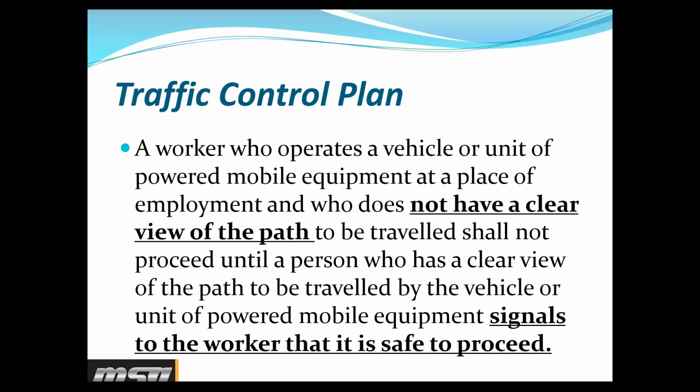These variables limit the clear view of sight and require the need for a signaler. I actually knew of an automobile dealership that drove into their dealership shop and they hit a fellow employee with a car because their windows fogged up and they could not see and they were not using a signaler. So again, this section really outlines the requirement for utilizing a signaler that can assist if you do not have that clear view of path or sight when moving a piece of powered mobile equipment.